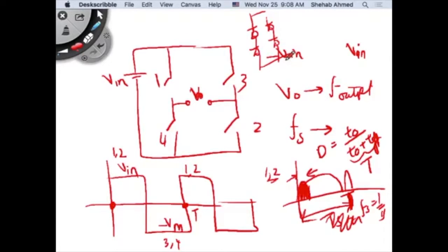If it's a different thing, a circuit that's intelligent enough to detect, okay, I have too much harmonic content, so I'm just going to be heating up my board without transferring a real amount of power to the system, right? Lots of current and voltage harmonics, for example, or if this is a current waveform, lots of current harmonics with no power transfer. Then it's a different problem. Some equipment will tell you, we allow for voltage distortion of a certain amount. You exceed the voltage distortion, I will shut down. It's like the thermal shutdown we talked about the other day.